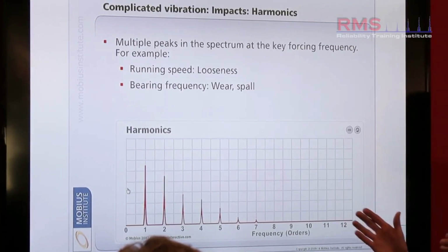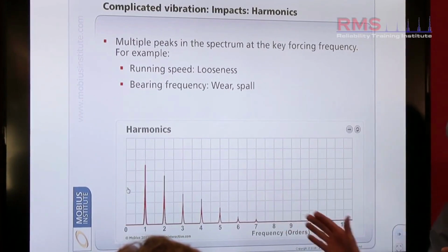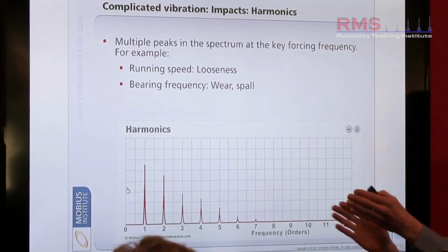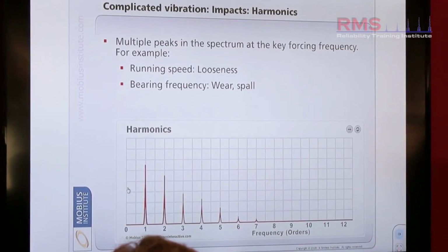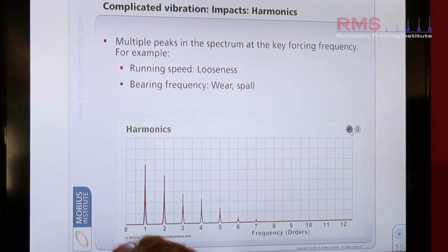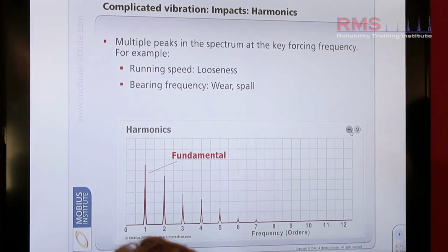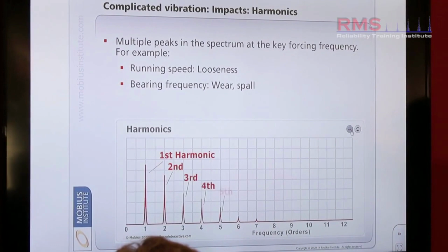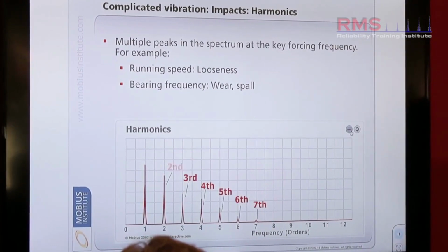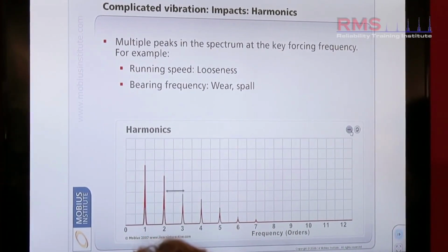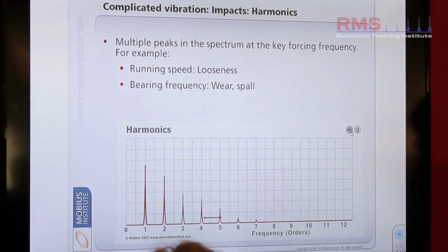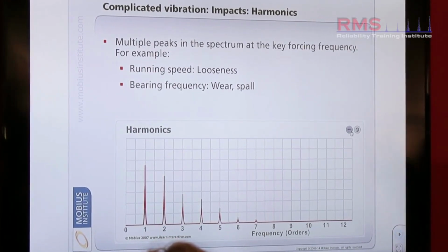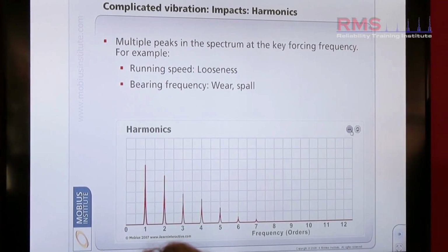Characteristics that we call harmonics. Lots of them. Here we've got 7. Typically we see a lot more where something might be loose. Harmonics, like the echo scenario, are equally spaced peaks that appear in the spectrum. So that's distinctly different to what you saw just now with a smooth vibration, where there was only one single dominant peak.